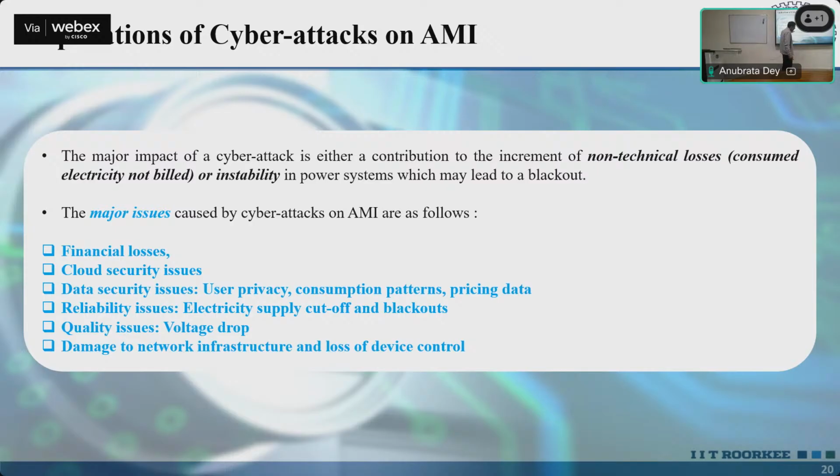Now let us concentrate on smart meter only, because we do not have the other type of case study like EV and all. If you just do the attack on smart meters, then that is going to lead to non-technical loss. This is a major concern for the utility. Non-technical loss means it is related to the energy consumed that is not billed. That means though I have consumed the energy, I am not paying the bills.